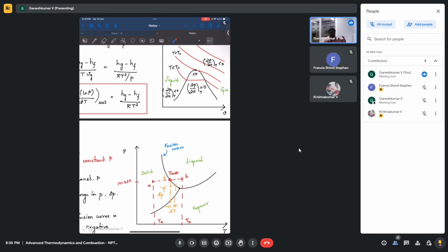There are different saturation models. Those saturation models will give you T saturation for solid-liquid conversion, solid-vapor conversion and all. But I think you may not be able to find tables exactly. So there might be models where, let's say, my T sat is nothing but some constant times pressure plus e power something, log of something, all these things it might depend on.